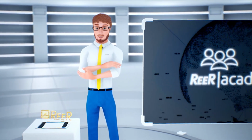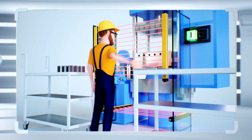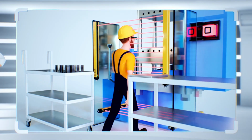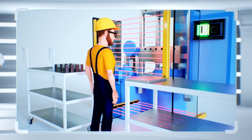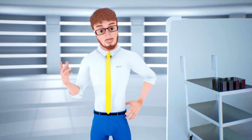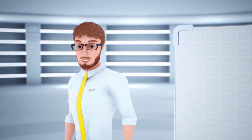Finally, the risk assessment should be repeated after the safety measures have been installed, with the aim of verifying that the machine has become safe to an acceptable level. Of course, there are specific regulations that define how to carry out a risk assessment. More details can be found in the EN ISO 12100 norm.